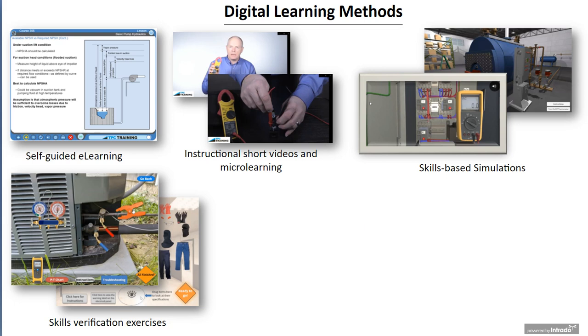There's a bunch of electrical PPE, and you need to dress the person on the screen in the right PPE. It's fairly simple, just drag and drop the items on the person, but with all the options available to you, there's only one correct answer. So it's really a good way to practice. Do I know what I need to wear? Do I need a balaclava, or a face shield? Do I need class 00 gloves or class 0 gloves? You get a chance to look at the arc flash label, go back to the dressing room, and really practice these skills. Dressing in the correct PPE is definitely a skill. It takes practice, and sometimes people overlook that as part of the process.